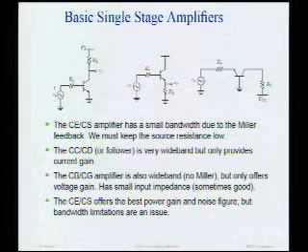There is feed-through from the input to the output, which does produce a 0 in the transfer function. But it's actually not temperature stable, right? And it varies a lot with process, right? So if I have this, the gain of this device is GM times R. GM varies over temperature, it varies over process. R varies over temperature, varies over process. It's not a very robust amplifier, right?